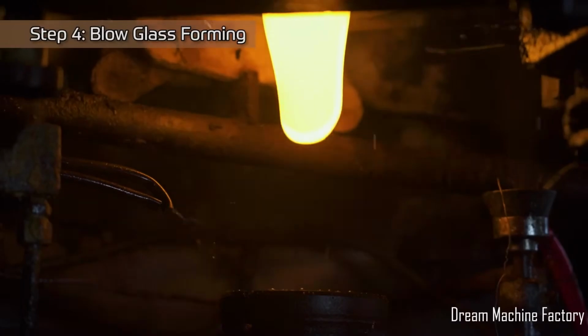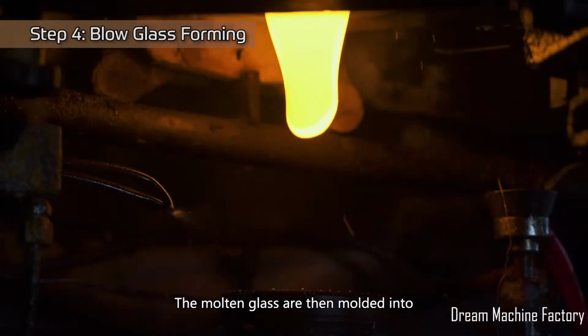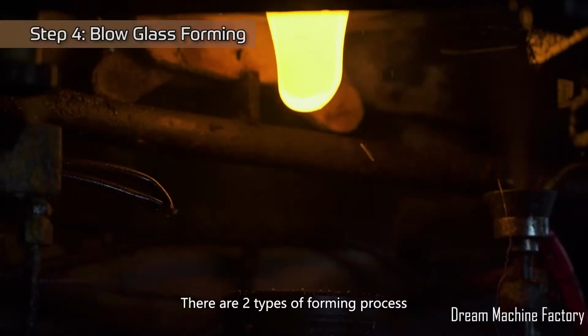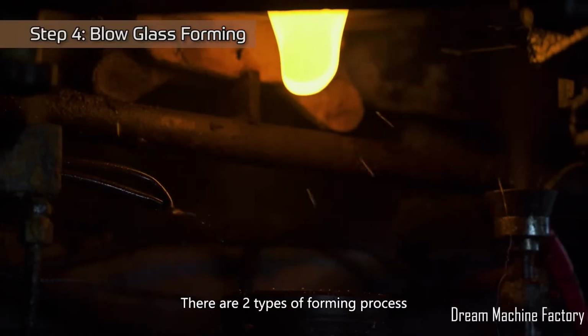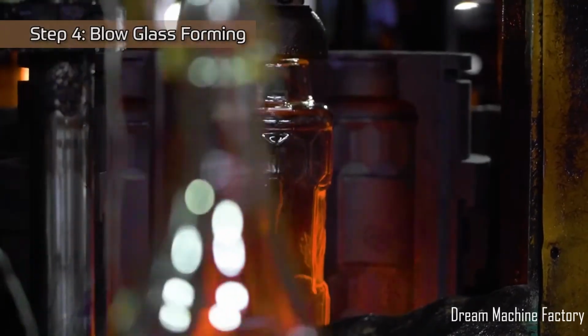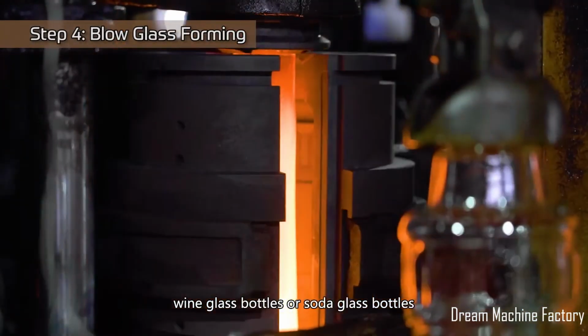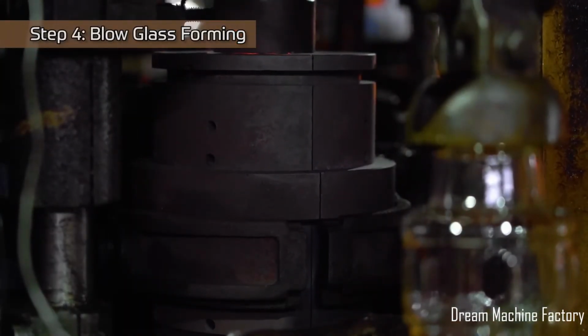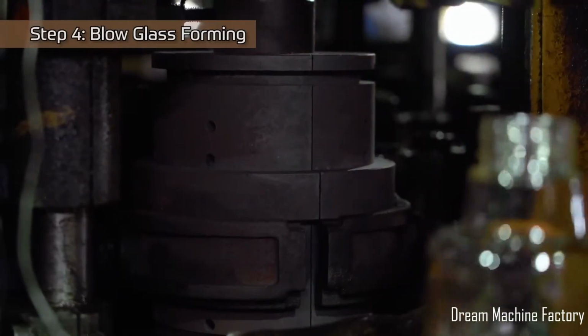In Step 4, molten gobs of glass are shaped into bottles through specialized forming methods. For narrow neck bottles like beer, wine, or soda, the blow-and-blow process is used. Compressed air shapes the gob into a preliminary form called a parison, which is then reheated, flipped, and blown again to achieve the final contour.